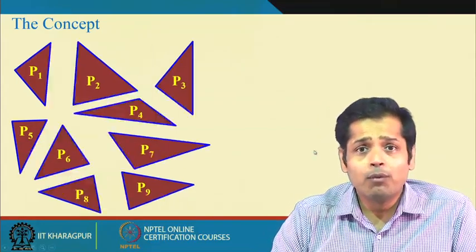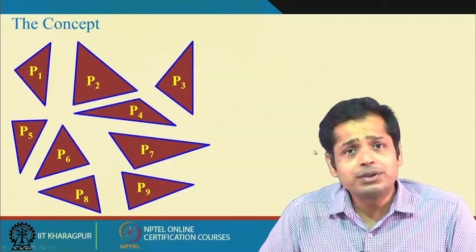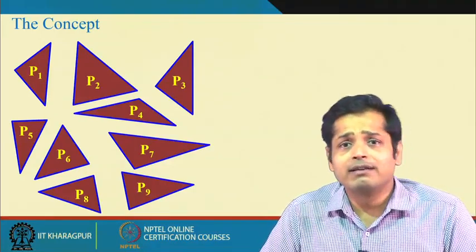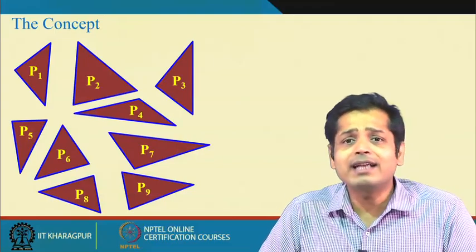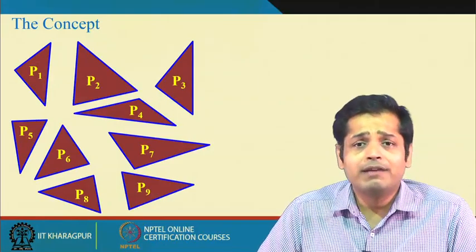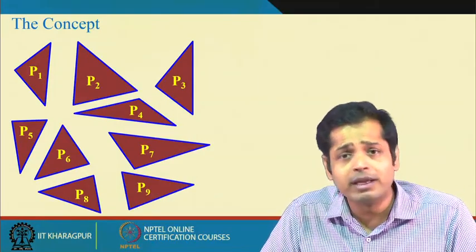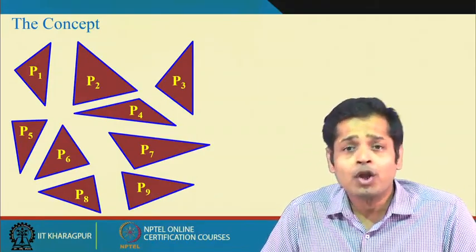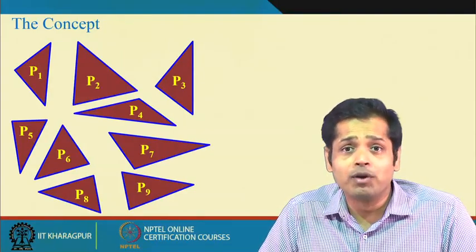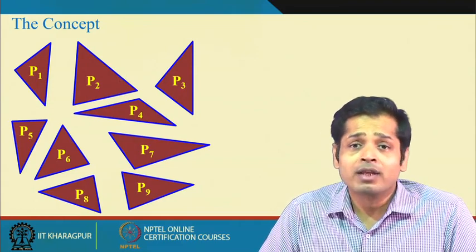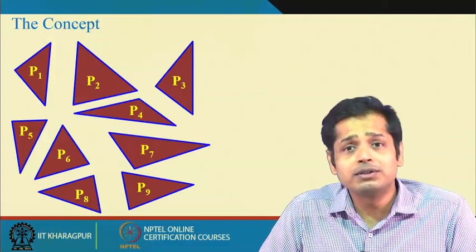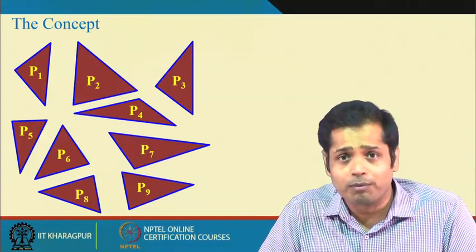Then what we do is we calculate the area of each triangle separately and then sum them to get the area of the entire shape, and that is the core concept behind matrix method of structural analysis. Even though the structures are very complicated, with many members and very large scale, we divide the entire structure into small elements like small beams and truss elements, and then write equations for each small element, each a small sub-problem.